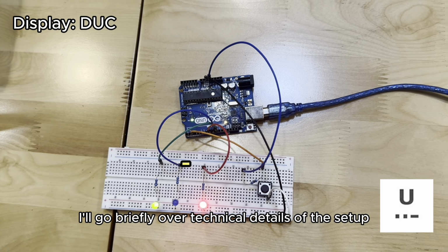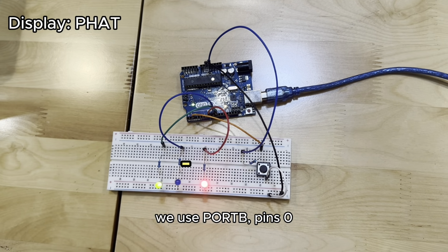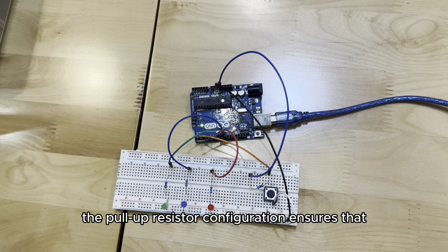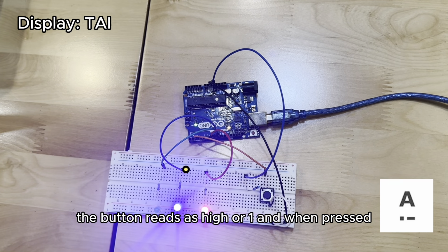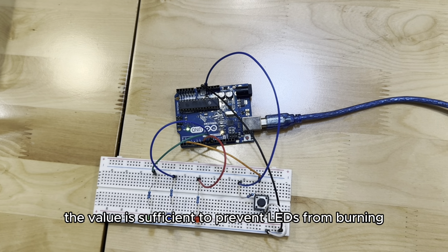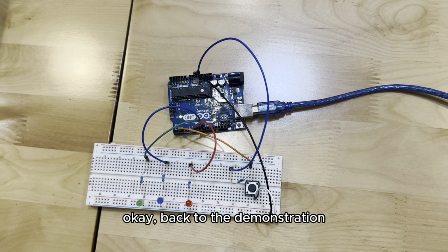While the initial stage is running, I'll go briefly over the technical details of the setup. We use port B, pins 0, 1, and 2 for the LEDs, and pin D2 for the button. The pull-up resistor configuration ensures that when unpressed, the button reads as high or 1, and when pressed, it reads as low or 0. All resistors used are 220 ohms. We think that the value is sufficient to prevent LEDs from burning. Okay, back to the demonstration.